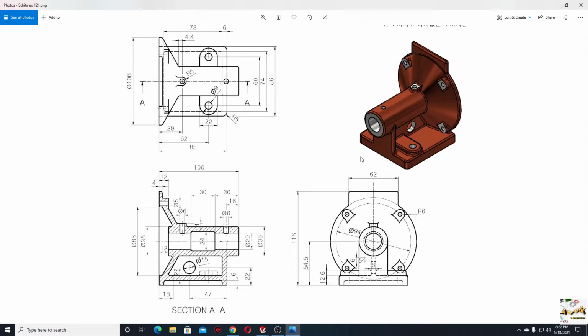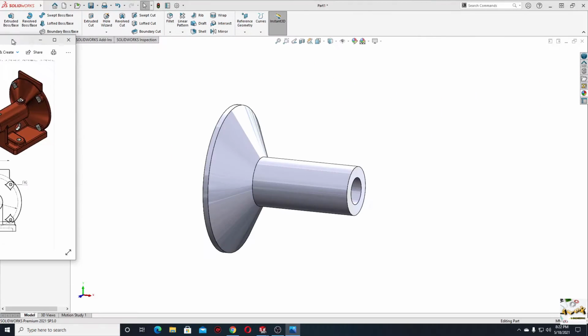And now we'll have to make the bottom from this part, which is this rectangle. So let's do this. We can see here the thickness 12 millimeters, and we can see here that will be collinear with this line here. We can see here the total length is 85, and here will be 86. And let's do this.